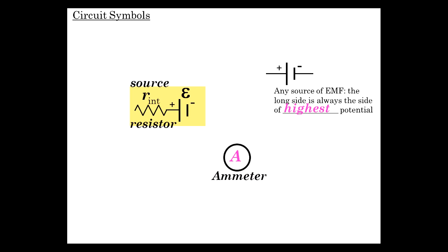Now, how do we include an ammeter? Ammeter is a current meter. The current in the circuit has to flow through the meter without disturbing the function of the circuit. That's crucial for the basic ammeter and voltmeter. They have to be included in the circuit to measure the quantity without disturbing the circuit. So an ammeter, since it's measuring current, has to be in series with the circuit.